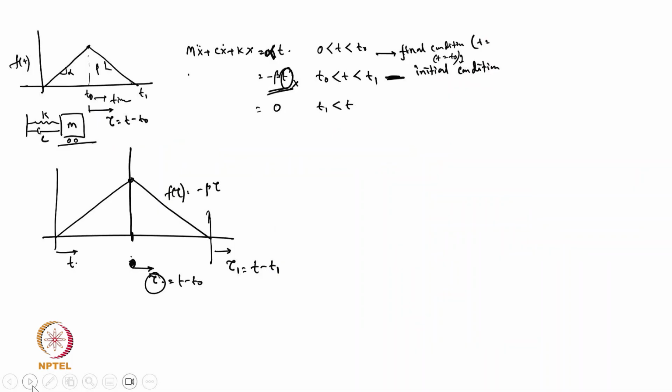Then we checked, suppose the forcing functions are not thoroughly the same, and they are changing over some time span, how to consider that. For example, there is an increasing force and a decreasing force, like we have applied some force that goes up and goes down. Then we have to divide the full time domain into those steps. Once it is increasing, we consider the increasing force condition and solve it. Then again it is decreasing, so we do it, and then it is a free vibration once there is no force applied on that.